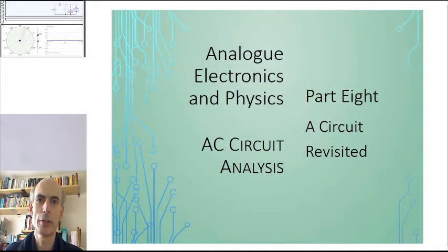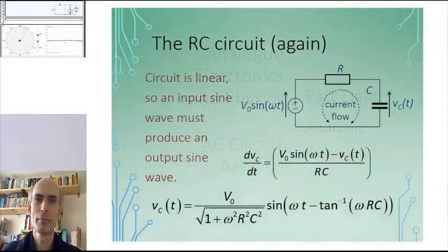For the final video in this short series, I want to go back and look at a circuit that we first came across when we started studying time-variant circuits. This one. You may remember that at the time I said that I wouldn't bother to solve this differential equation because I would be introducing a technique later on which allowed you to work out the voltage across the capacitor without having to do any calculus. That time has now come. We can use this technique of phasors to solve this circuit.